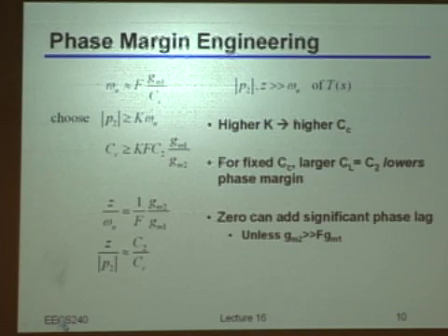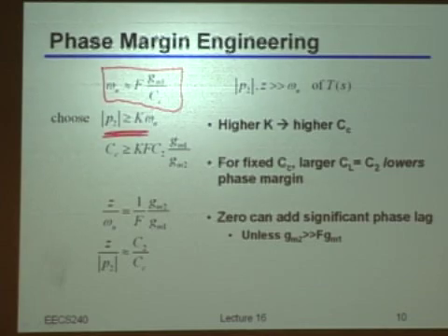And that's actually a bunch of expressions that help you understand how to actually engineer this phase margin. We walk through these slides and then we conclude for today. The whole idea is, as we were writing already, all the expressions we already had from previous calculations. This is the crossover frequency of your loop gain. And one thing that you want is to push the second pole at a factor of k times the crossover frequency. That's normally the problem of getting the phase margin that you want or stabilizing your amplifier.